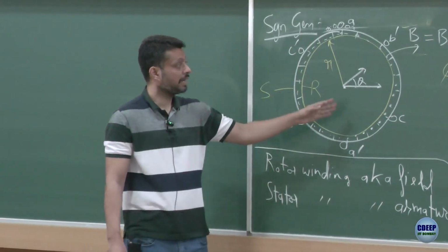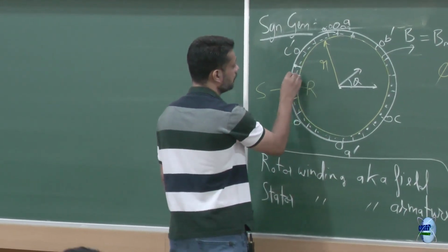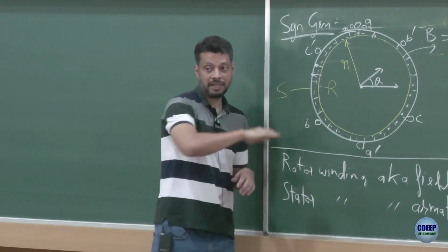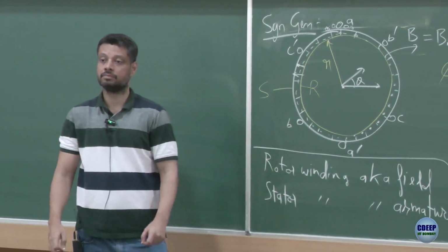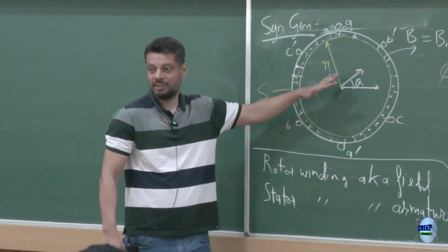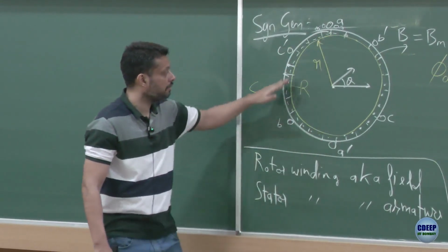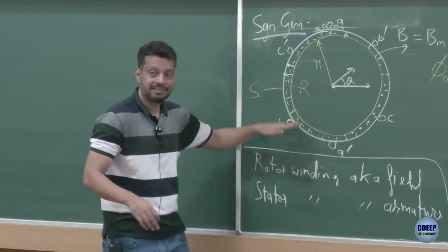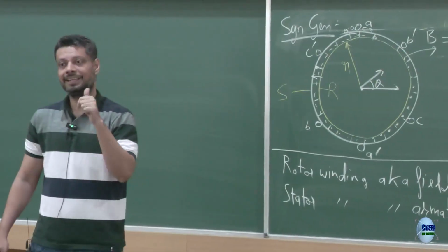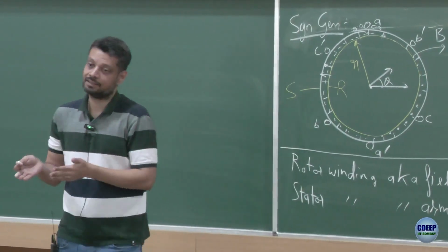When we are calculating flux, why are we not doing what? The lines are perpendicular. This is something which we have studied long back, right? All the lines in the air gap are perpendicular. In this plane they are flowing some way. We are not integrating from this point to this point. What we are saying is whatever is the total flux, the total current entering this surface would flow from this side, KCL, right? If you remember, we have drawn electrical equivalent circuits of magnetic circuits, where flux behaves the same way as current.